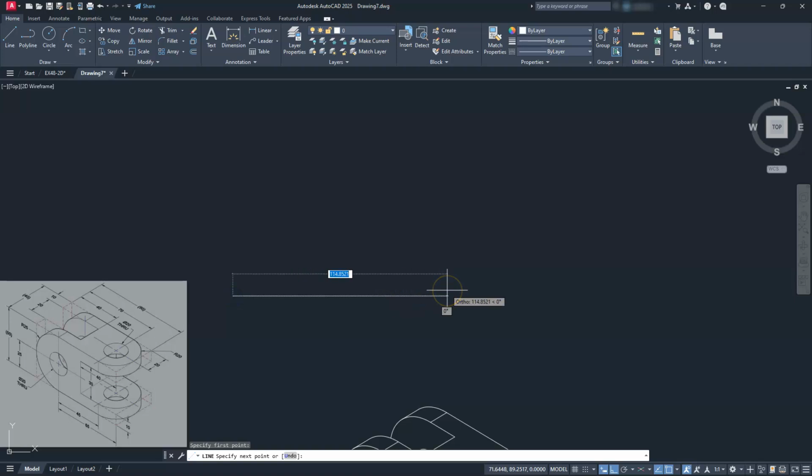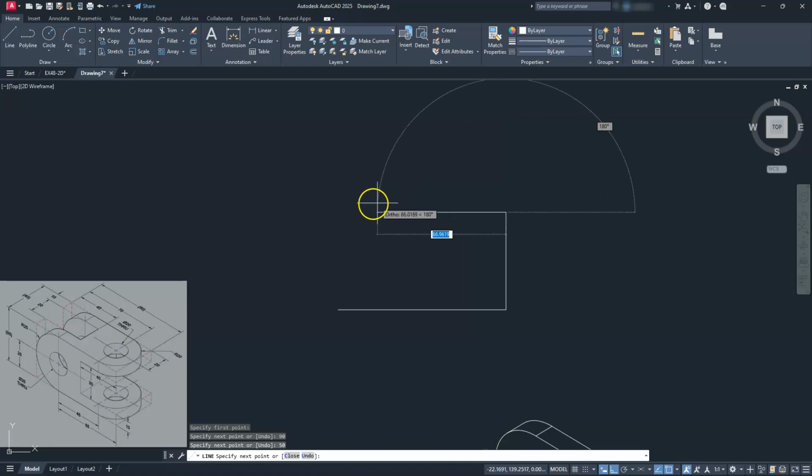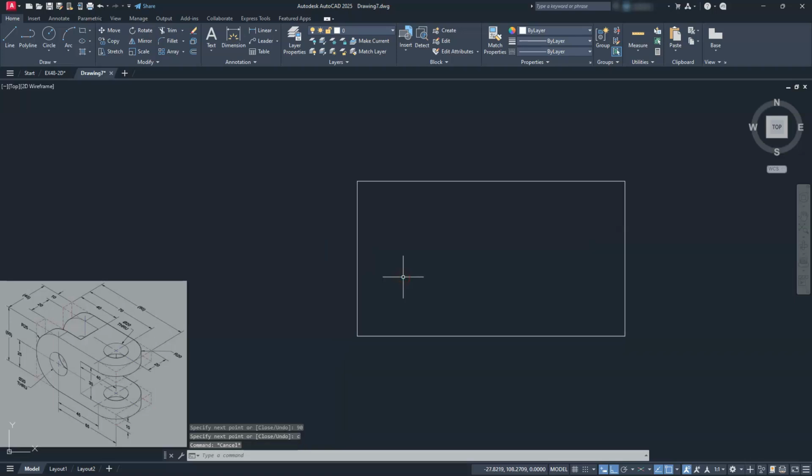And I'm going to create this just like how we did with the isometric. So I'll go ahead and create a square here, or rectangle actually. So I'm going to draw 90 going this direction. We're going to go up a height of 50. I'm going to come back to the left here 90. And then I'll just go C for close, right? Okay.